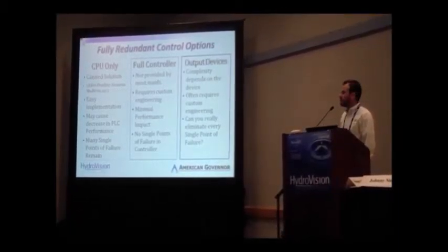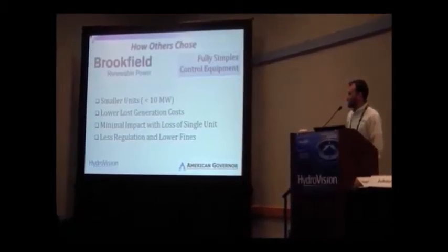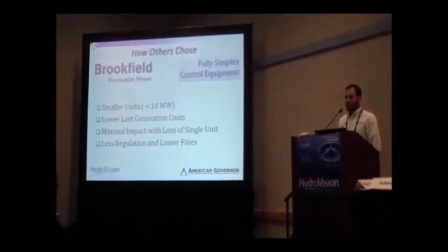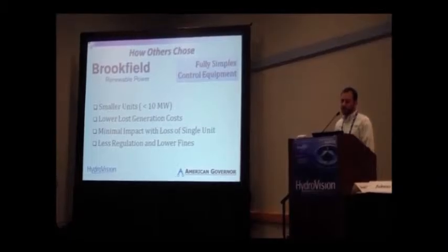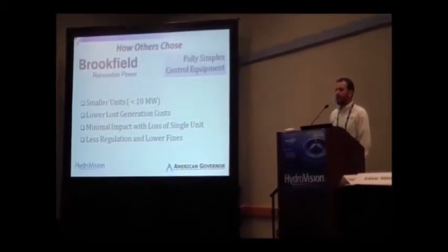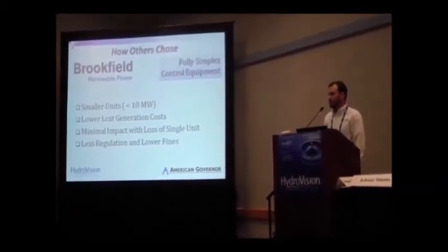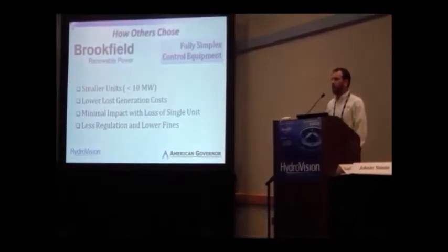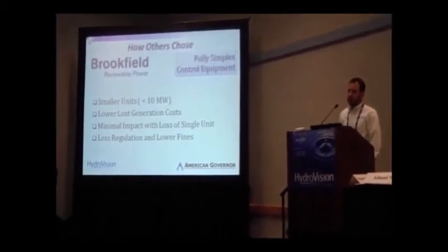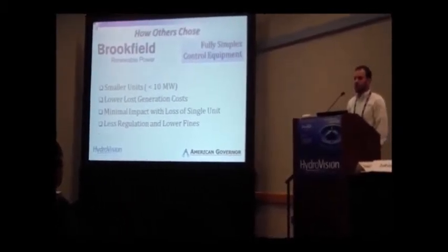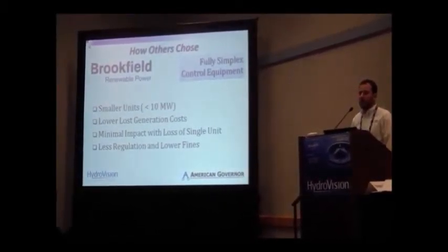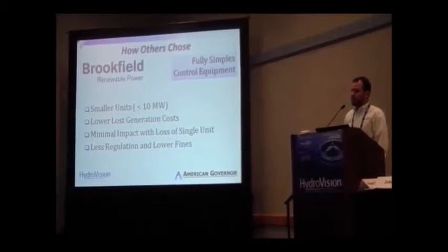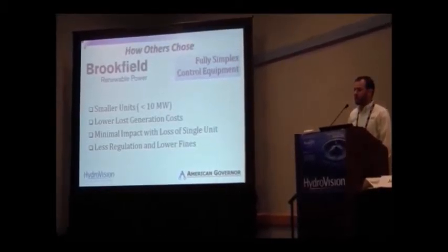They're all valid configurations. So I'm going to choose a few utilities we've worked with and show you their situations that drove the decisions they made. Brookfield Renewable Power has many hydro installations in New York and Maine. Many of them are under 10 megawatts, small units. So they chose fully simplex equipment. One power supply, one controller, one output.